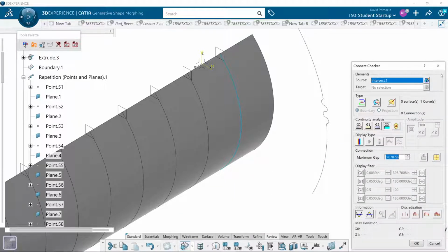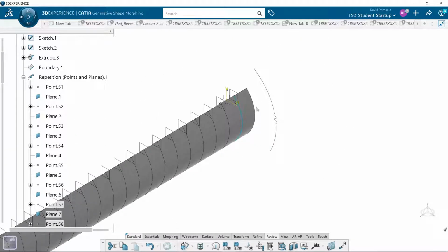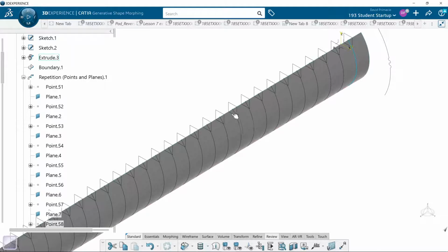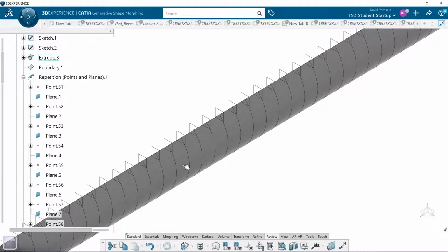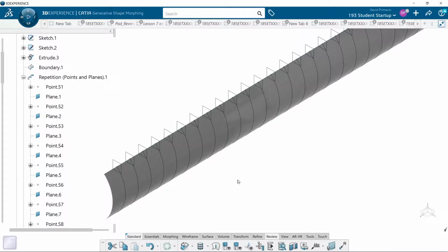This won't do it. We used to be able to pull up a chart on this and it will show us a graph, which I can't find the icon that will do that now. But we could pull up a graph and we could see the chart if it was going to go up and down, positive, negative values on that one particular spline, because sometimes it's hard and you just got to kind of spot check that surface and check each curve as you go along that surface for your analysis to see if there's any issues.